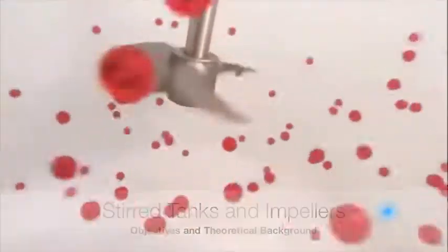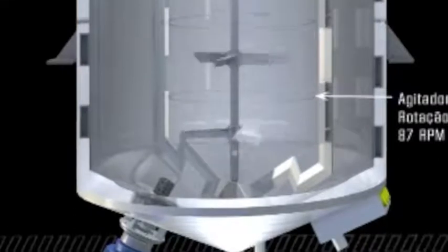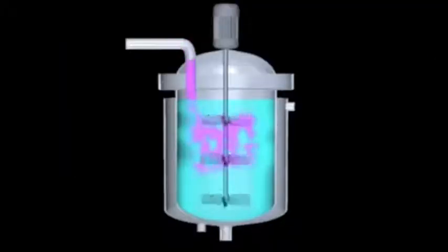In industrial practice, stir tanks are used in a variety of important operations to perform many different processes. The mixing process carried out in stir tanks is particularly important in fields such as pharmaceutical, plastic, and petrochemical. The main purpose of mixing is to provide a proper contact between two or more components in order to optimize the mass transfer and to obtain a product with the specified properties.